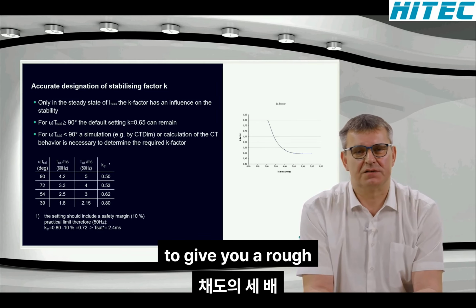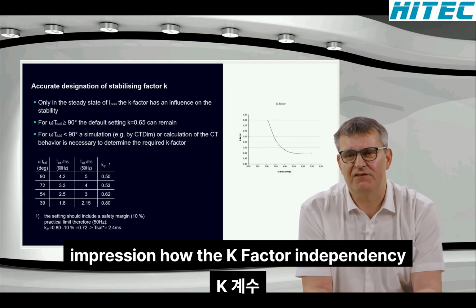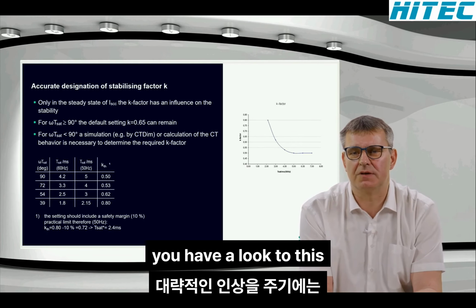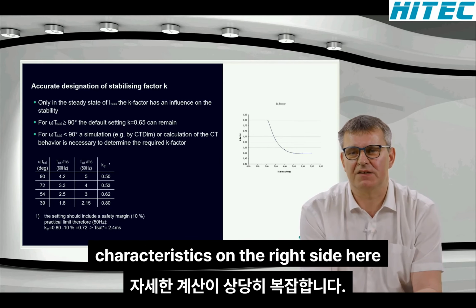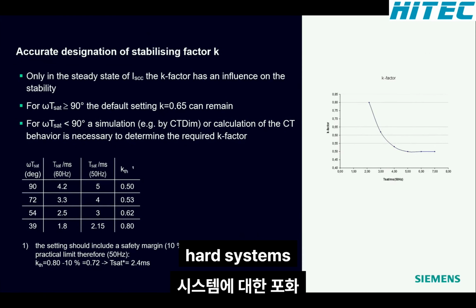To give you a rough impression of how the K factor in dependency of the saturation-free times looks, have a look at this characteristic on the right side. Here we have the saturation-free time for 50 Hertz systems.